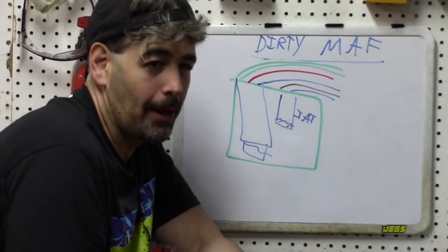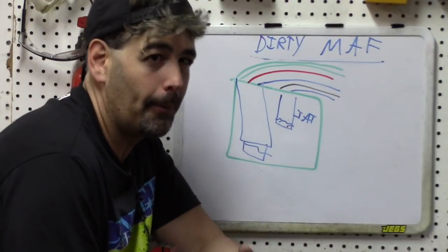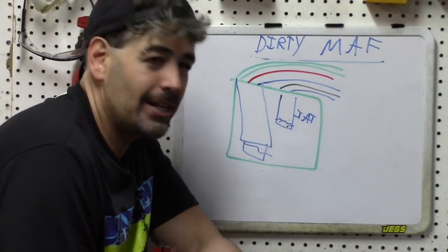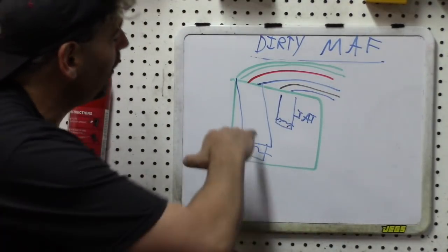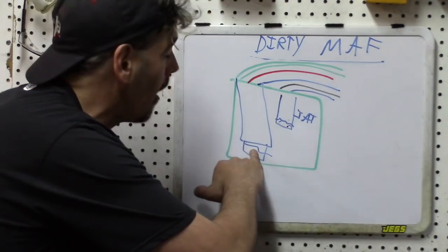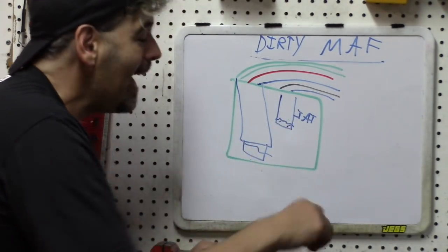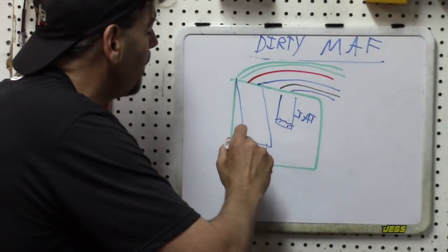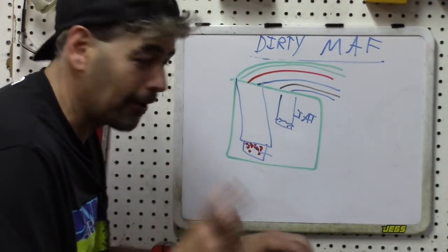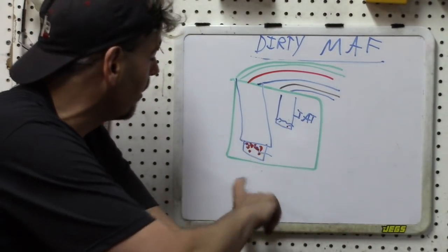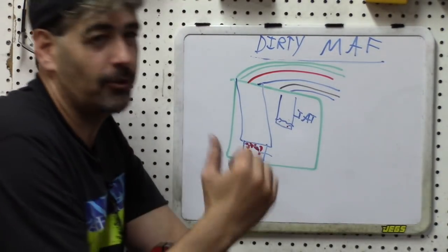After replacing the fuel pump and it did not fix the car, I obviously had to swallow the price of the fuel pump because I was wrong. And I could not for the life of me figure out what was wrong, did a little more research, come to find out that the mass airflow sensor wire on this model is kind of hidden in this composite unit. And of course, when I looked at it, it was absolutely, completely covered with dirt. When I went ahead, used my throttle cleaner or my mass airflow sensor cleaner to clean off all that dirt from the correct component, the car just absolutely ran beautifully.